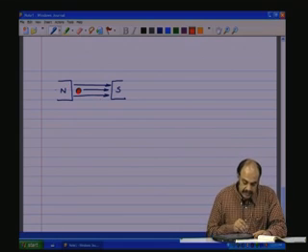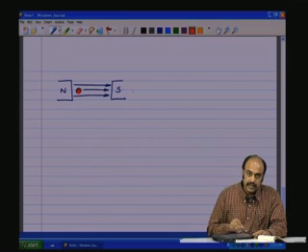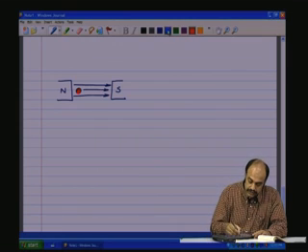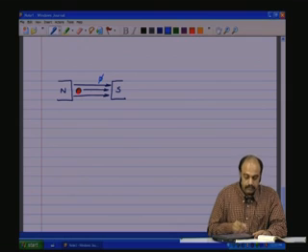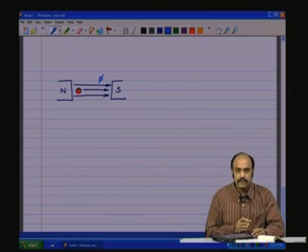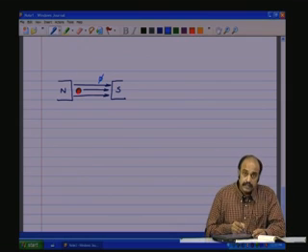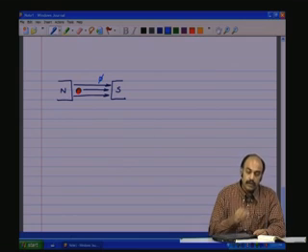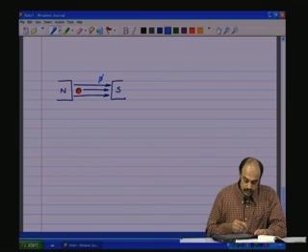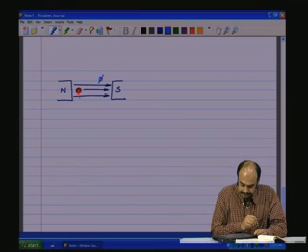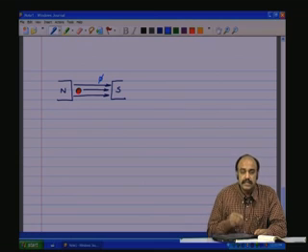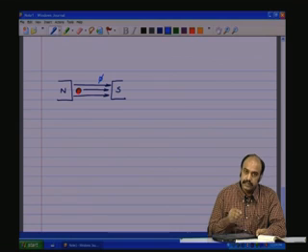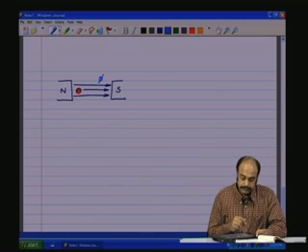If the amplitude of the flux phi here is changing, then there is a d phi by dt, and this results in an induced EMF in the conductor, which will result in a current to flow through the conductor in a specific direction. So, therefore, what is essential is a changing field for a voltage to be induced in the conductor and thereby a current to flow in the conductor.